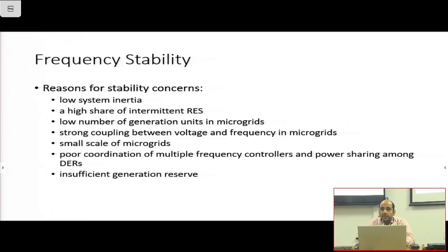That automatically means that with large renewable integration, the renewables will not add large inertia, and also the renewables will have variability and sudden power change, like the ramp issue that we discussed. Sudden power change can again lead to frequency stability issues, because certain power changes will lead to frequency deviation, and if the frequency deviation exceeds a certain band, your protection system can kick in. Some trippings may happen, or your frequency may fall and collapse.